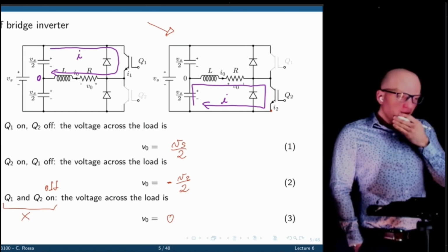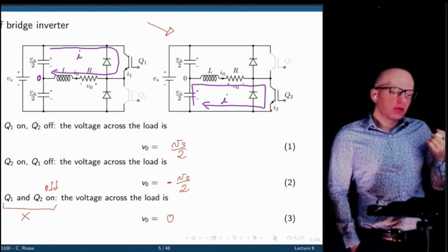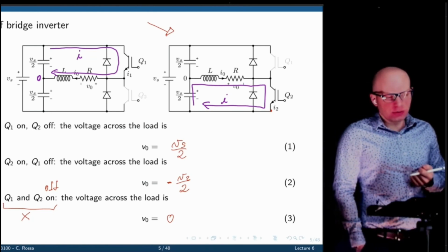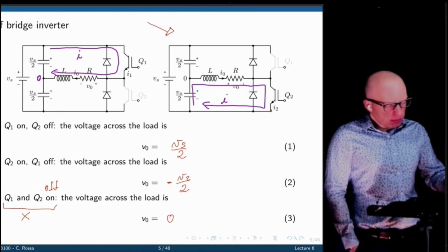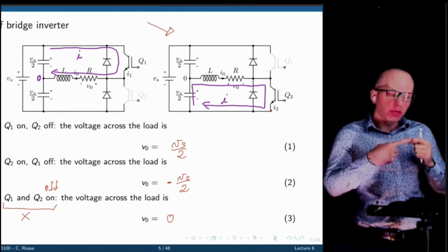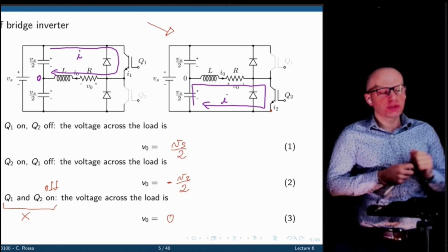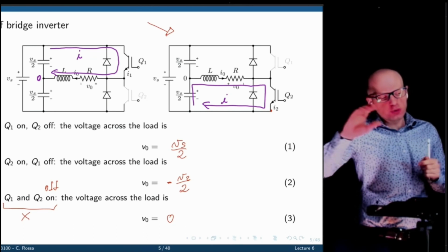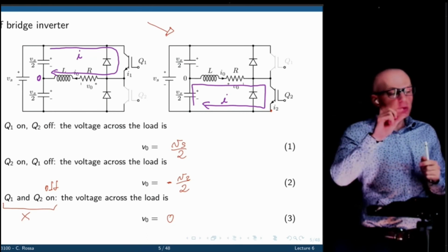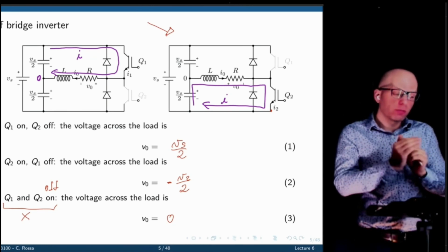Well, not really. The idea of having the diodes is to use them as freewheeling diodes. We notice in this mode of operation, we can only operate one transistor at a time. We cannot operate both at a time, we create a short circuit. So when you close transistor 1 and you have to open transistor 2, we need to give a small time delay. During that interval, both transistors will be open.